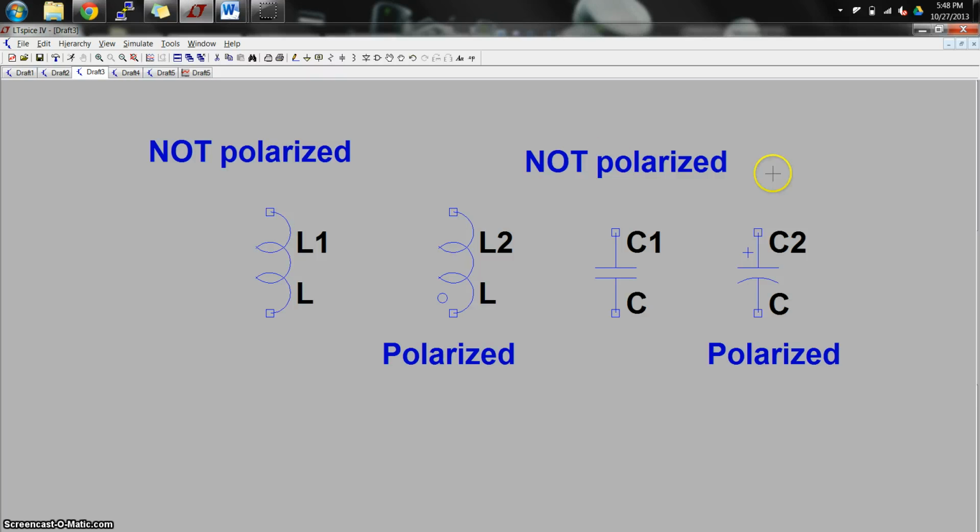It is possible to blow the top off your capacitor. It's happened in IME 156 before. If you hook your capacitor up backwards and you apply power, the top can literally pop off. So just something to be careful about.